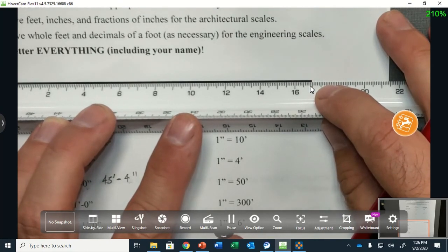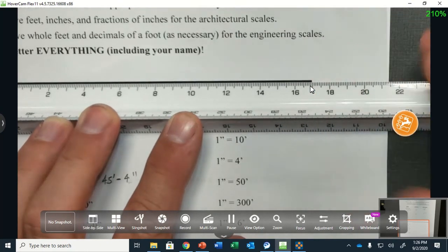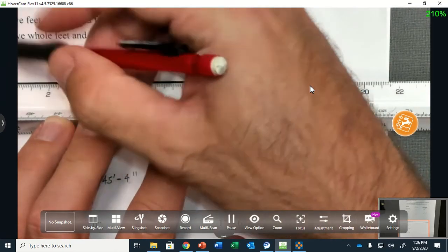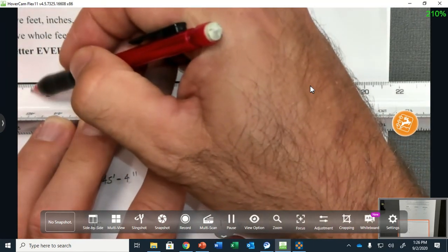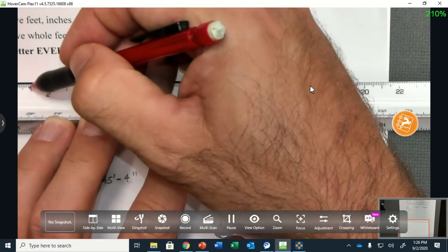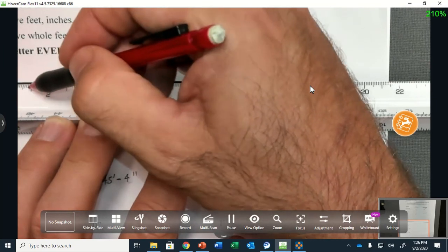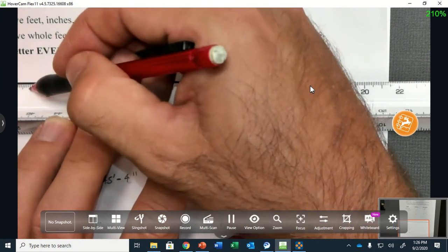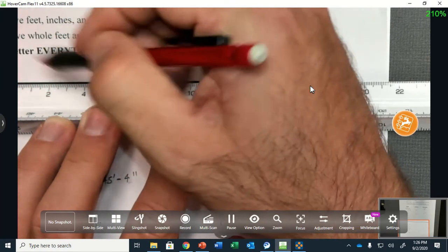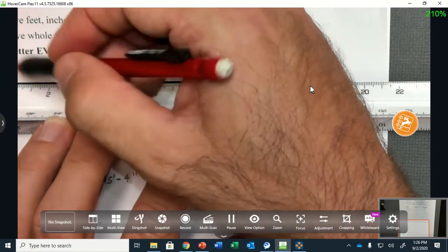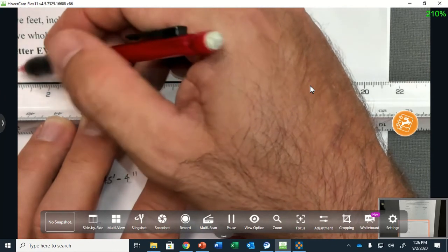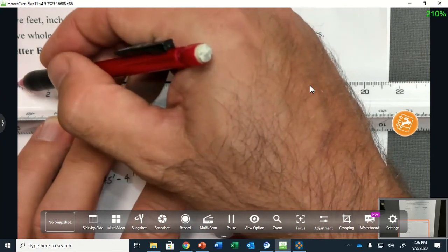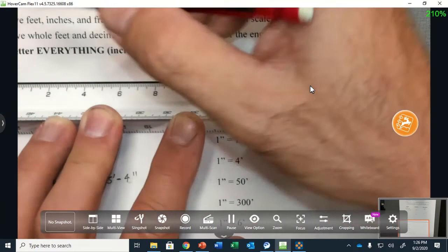Okay. First step, what is the value of each of my tick marks? I know there's another 0 here. So you find the 1 spot. So I know that's 100 feet. I know there's 10 tick marks between here and here, here and here, here and here. So each tick mark is 10. 10 times 10 is 100. So my accuracy is 5 feet, okay?